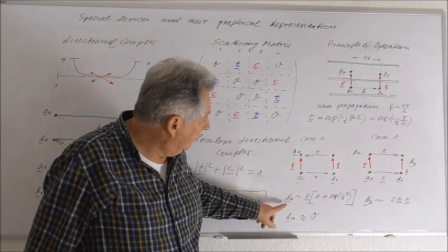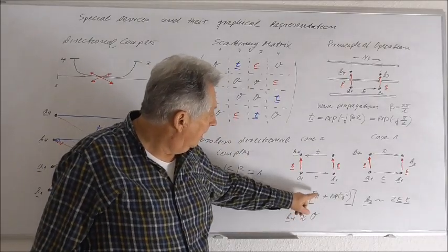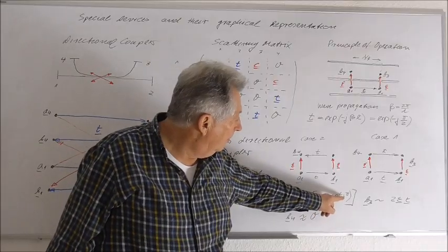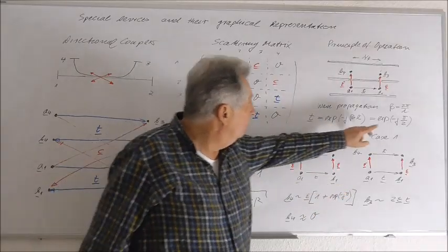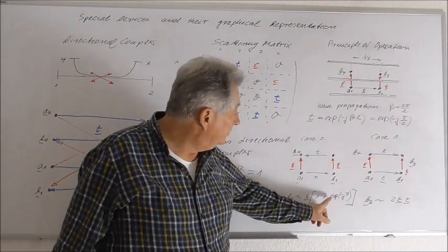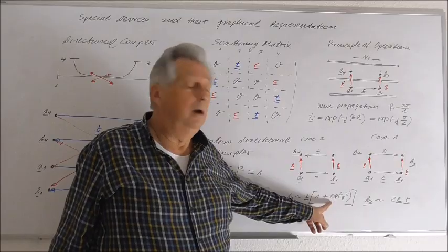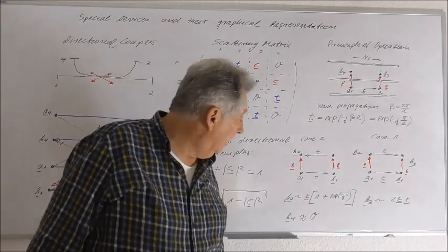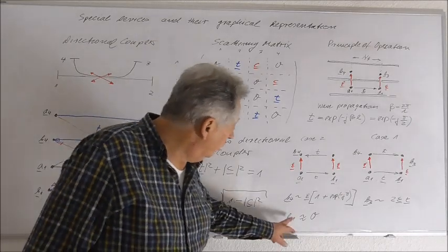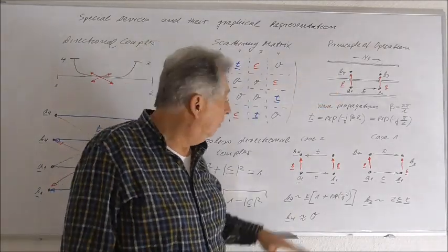So we will have that B4 will be proportional to the coupling and 1, but here we have the exponential function e to the minus j pi, because they both will multiply to each other, and as you know, if I have an exponential function of minus j pi, then of course this is essentially minus 1, so that there will exist no coupling to port 4.